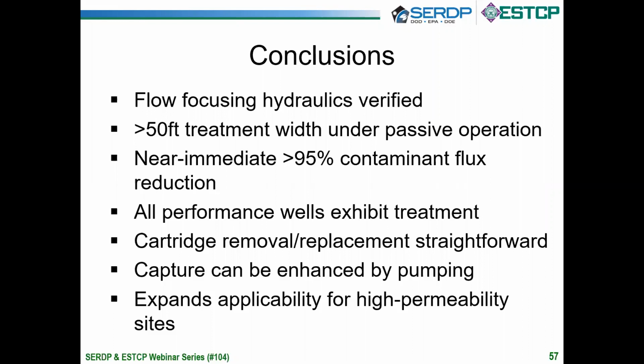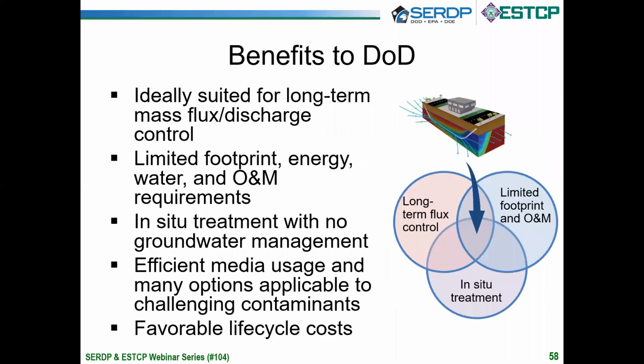Also, the cartridge removal and replacement is very straightforward. As part of some of the testing, we mobilized a rig and pulled the cartridges out and pushed them back in, and they were quite easy to do. So we anticipate removal and replacement as needed is a straightforward thing to do. As I highlighted, the capture or treatment width can be enhanced by pumping, which expands applicability for high permeability sites.